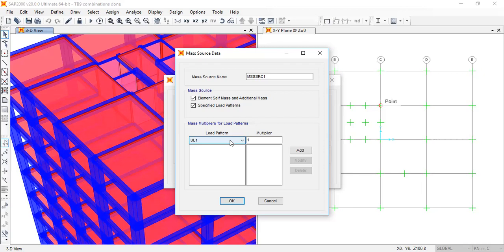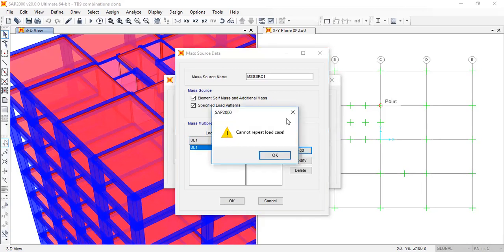I will take 60% of the services, which is service load 0.5, 60% is 0.3. So 0.3 plus 0.7 is 1. And then partitions, I will take 70%, so partition load 1 into 70% is 0.7, so that everything becomes 1.7 when you add it, right?